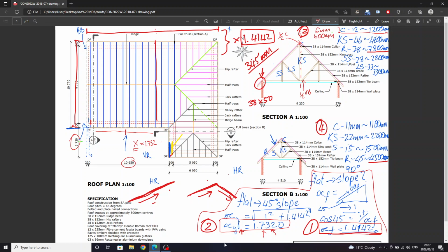The flat dimension is still having to convert itself by 1.4142. Same story here. This flat dimension still has to convert itself to get to that. It is not concerned with what exactly is happening with the roof, but it's only concerned with how it needs to transform itself to get to this slope. Okay? I don't know, it shouldn't keep you up at night.